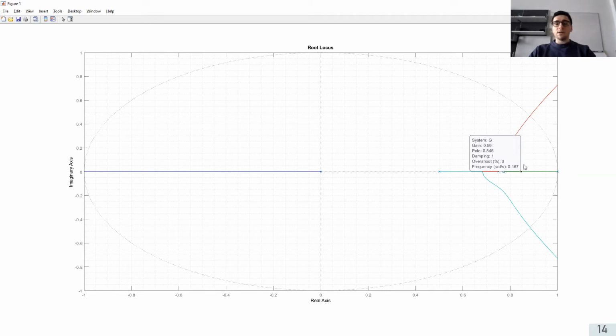So with this design, you can look for where the gain of the controller is. It's only using the magnitude condition, okay? And probably you already know what the root locus is, but you can only place the poles on the lines, okay? If you want the lines to change, then you need to change the controller 0 that we already found before.